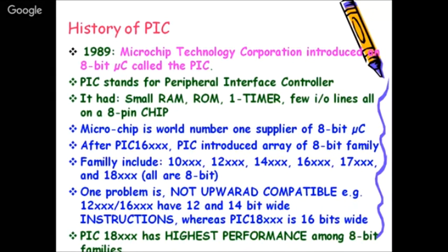So you'll see when we see that ROM structure where the instructions are stored, the program is stored, the fetching happens. It is 2 bytes wide. So at a time, 2 bytes are fetched from there. So the machine cycle is quicker and faster.